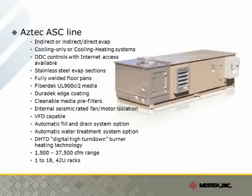The FiberDeck evaporative media is a glass fiber-based media that is flame and fire resistant when it dries out. Since there will be times of the year when evaporative cooling is not needed and there is no water flow, this is an important feature. The edge coating also adds durability to the media for less frequent maintenance, and the primary media is protected by a cleanable pre-filter. This can be particularly important in climates with lots of natural contaminants such as cottonwood seeds.